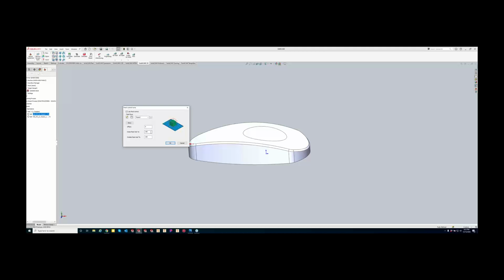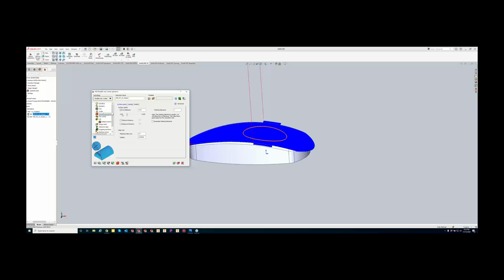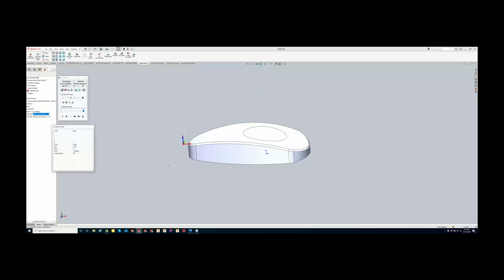On that one, I want it to do an inside feed of 200% versus the outside of that circle, which is going to be set to 100%. So that's exactly what Greg is talking about here. Basically, as we're feeding, let me get rid of this toolpath parameters, modify, I'll turn off our extensions here. As that tool is hitting that center, it will actually feed up through that area there. So let's just see it in motion here.